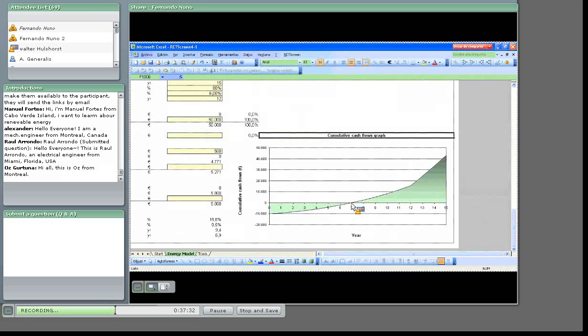Payback time in this case is about 7 years, and I can afford it without the need of any subsidy. So in this case, with these high wind speeds for the north of UK, according to RETScreen analysis, we would be in an economic range for a small wind project.